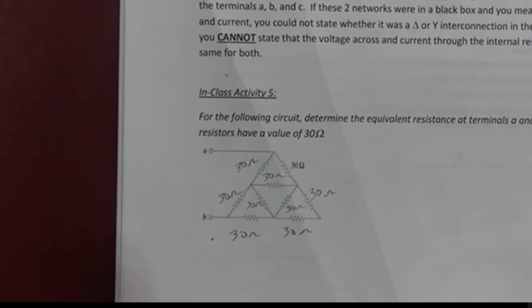Remember, I have to use the deltas to do a conversion. So you can't double count resistors. Every resistor can only be counted one time. So now it's 3. It's got to be 3 because I can only count each resistor one time, because I'm about to convert them. So they can't be double counted. So there are 3 deltas.